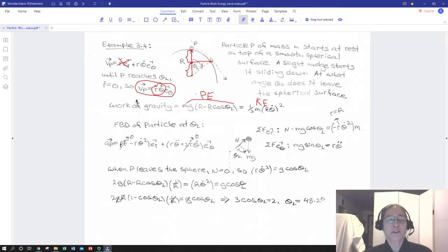So we've got the acceleration of our particle in terms of our radial component and our theta or tangential component. Our r double dot is 0, our r dot is 0. So we just have our radial component of acceleration as negative r, which will be big R, times theta dot squared, plus our tangential component, which is r theta double dot, or tangential acceleration at whatever point.